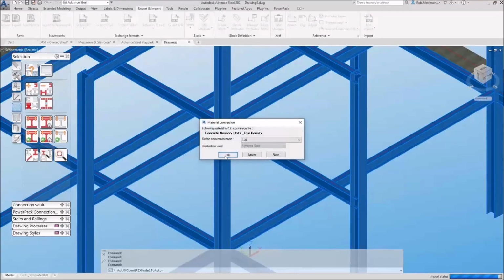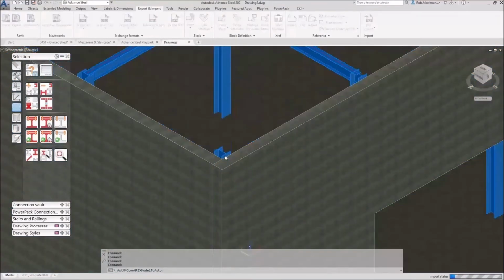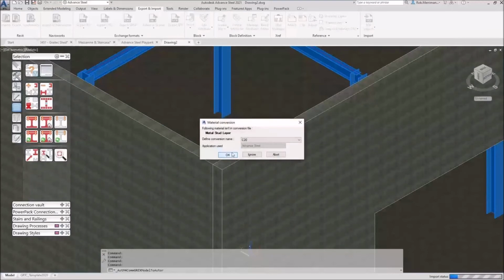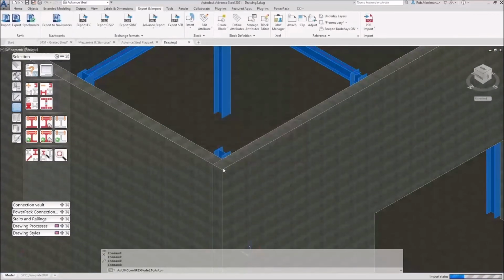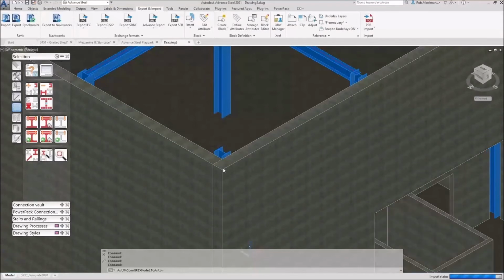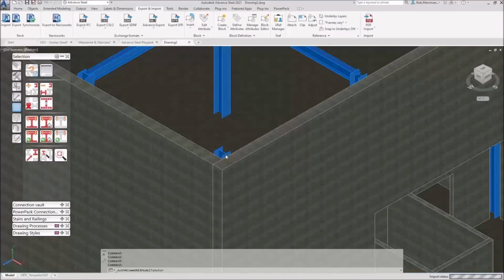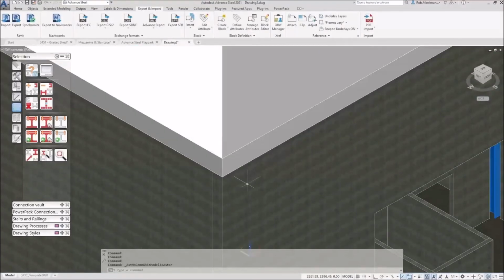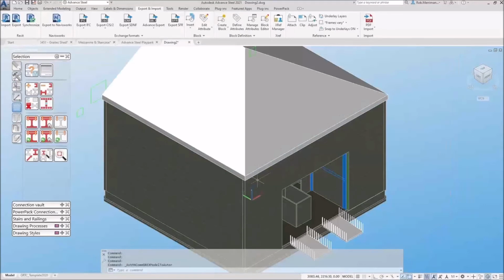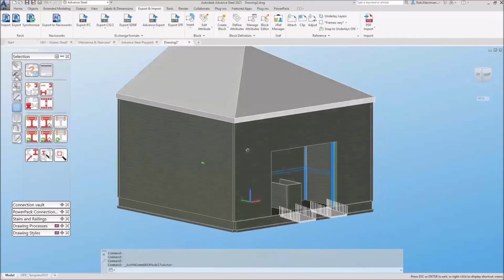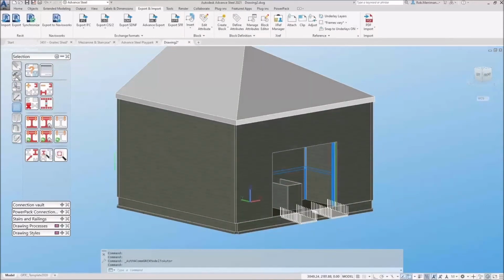And then you see in here, Revit is a completely different program to Advanced Steel. In Revit, you choose your wall, and then you can do the build up, and that will show in plan views and things like that. Advanced Steel just comes in with the finished thickness, and like the default roof, that's a material in Revit. Well, I don't have that in Advanced Steel, so I will just map it for now. But everything I'm clicking on at the moment is being logged in a database. So if you just randomly click OK on everything, it will remember that the next time you import.